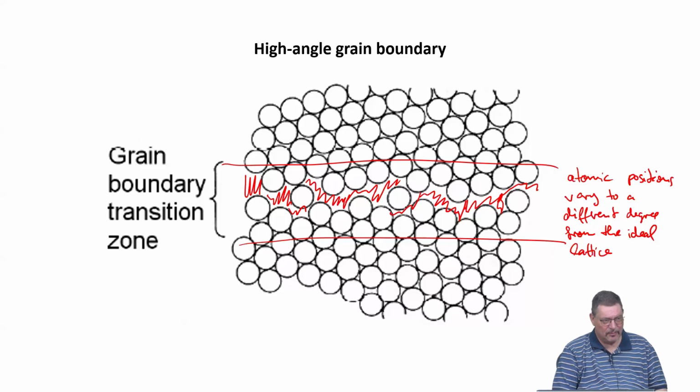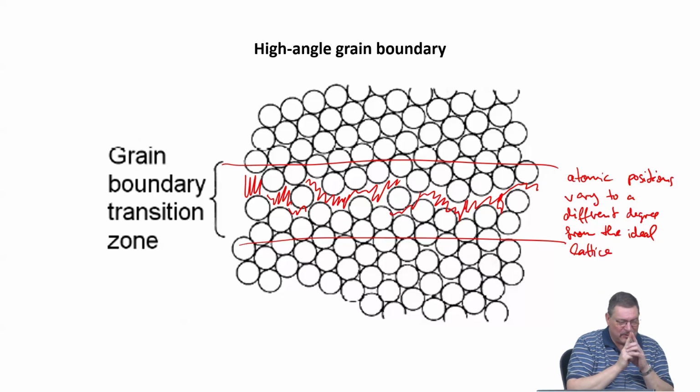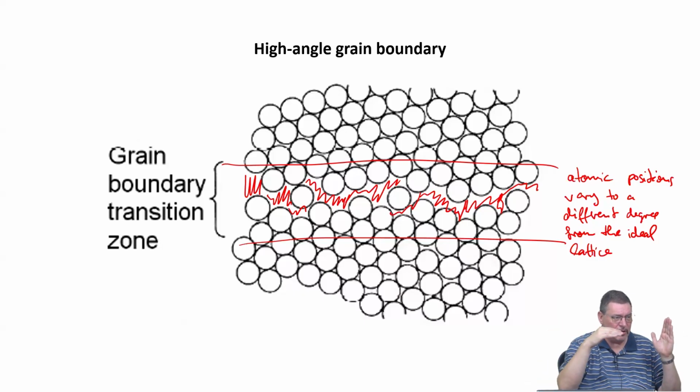So too many should be there. The gap is like one atom. This is absolutely correct what you say, but think about the very good paper by Gleiter and Pumphrey. They observed how a dislocation is driven by external stress into a grain boundary by doing snapshot TEM analysis and observing the strain field of a single dislocation. At that time, high resolution was not yet possible.